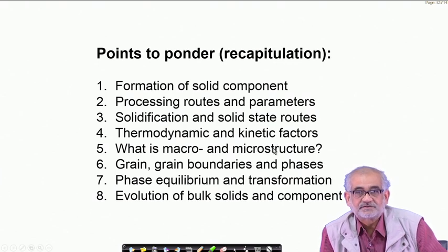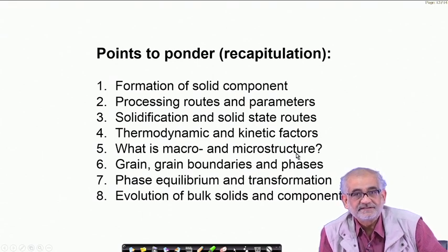So when we use an optical microscope or optical illumination by optical rays, we can reveal up to a certain length scale, and the resolution is up to a certain limit and not beyond. If you want to reveal finer details, then we have to use electromagnetic radiation of shorter wavelength, for example an electron beam, and in such situations we can see details which are not possible to be seen under an optical microscope.